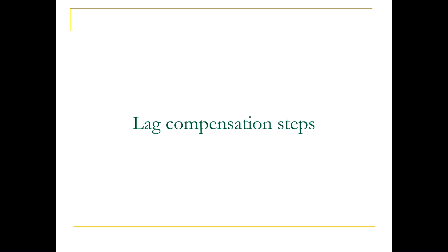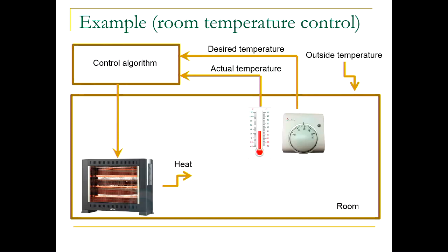All right, so now we can go through lag compensator steps. So slow me down if this goes too fast for you. We will actually consider the same example as what we did in the last lecture. So the idea is to have a slightly different set of specifications, but in this case we would again require increased phase margin. But this time we will achieve that with a lag compensator rather than lead. So in this case, the control signal is your input to the plant transfer function, and the temperature in the room is the output.